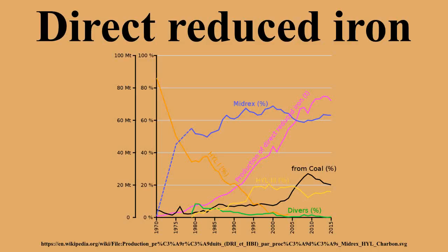The sponge is removed from the furnace, called a bloomery, and repeatedly beaten with heavy hammers and folded over to remove the slag, oxidize any carbon or carbide, and weld the iron together. This treatment usually creates wrought iron with about 3% slag and a fraction of a percent of other impurities. Further treatment may add controlled amounts of carbon, allowing various kinds of heat treatment.